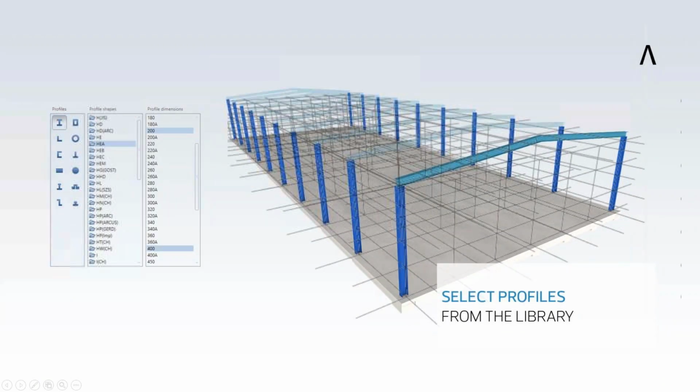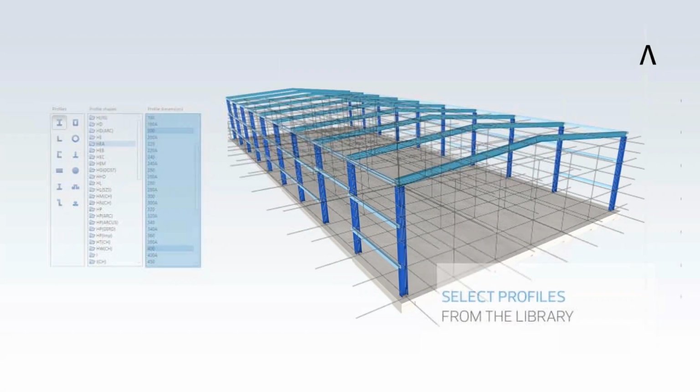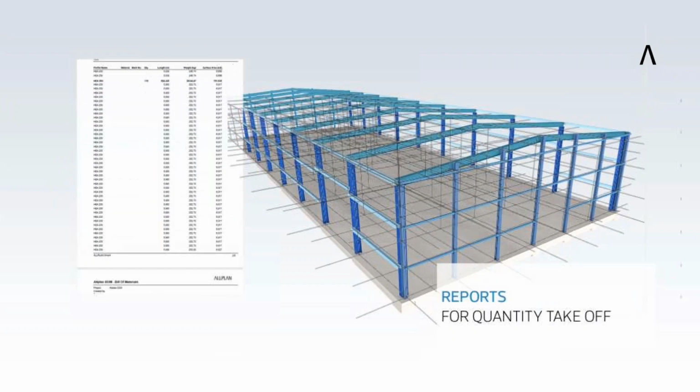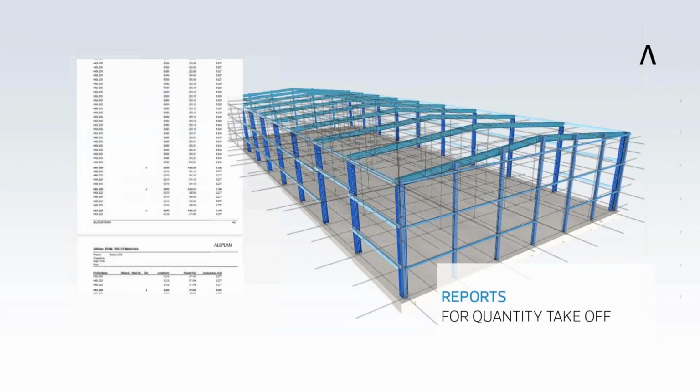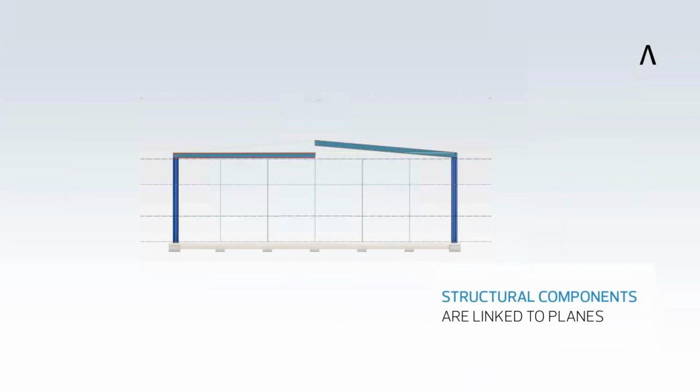And they imported the whole database of CA Engineer within Allplan. You just need to connect to BIM Plus, and you have access directly to CA Engineer profiles. And this means that if you use those profiles, you can get quantities directly from Allplan for the items you create. And not only quantities, but the detailing itself is there. So you know which profile and how to handle it.